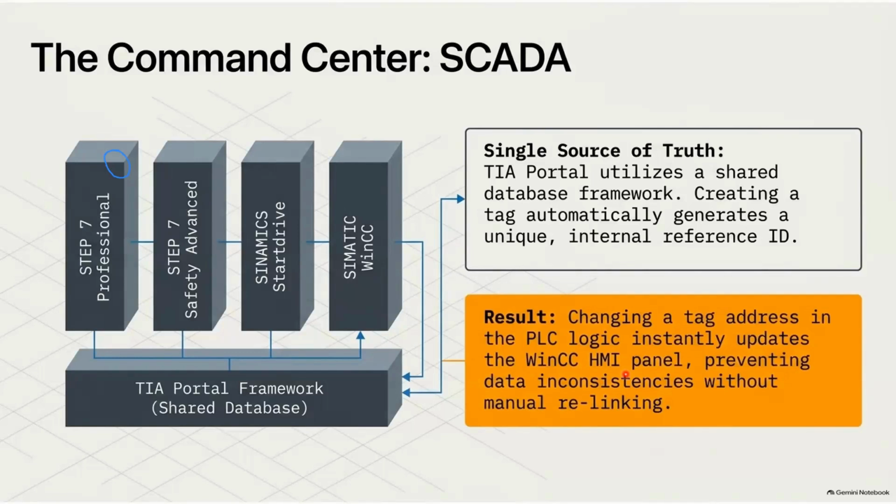Developing in the sense, you can make changes in the SCADA. And even for logic development, there is a separate software. So in total, three softwares will be there. One is the ladder logic or FBD development software. The other is SCADA, for SCADA development or production oriented. Both production oriented and development are the same, except for the license. After placing a license, it becomes a development software.